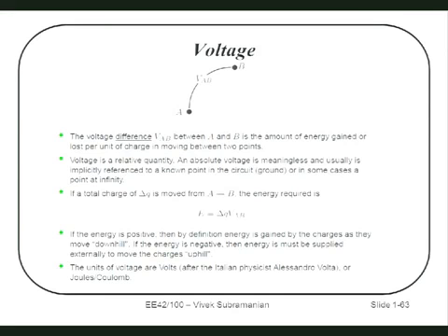No, it's not ground. The third one is ground. The little thing that's kind of shaped like a U is ground. The 2 flat pins, one is called live and the other is? Neutral. So the measurement of the voltage is between live and neutral. It is the measure between the 2 points. Neutral should normally be at ground. It's not guaranteed to be at ground, and if it's not, you have a problem in your household grounding. So, what is the difference between neutral and ground?